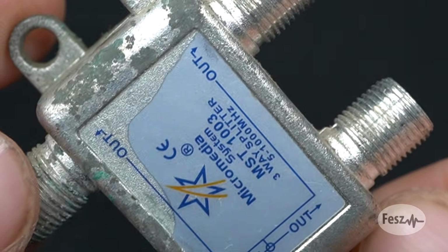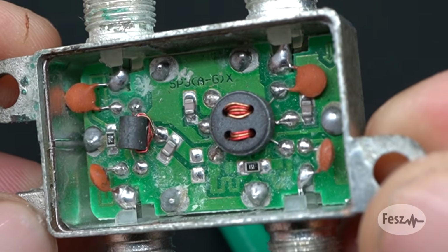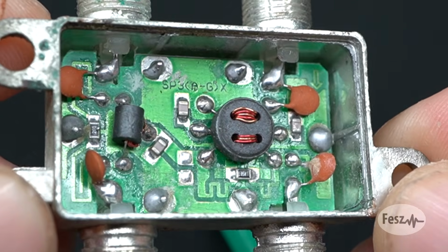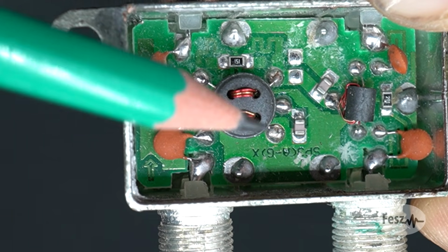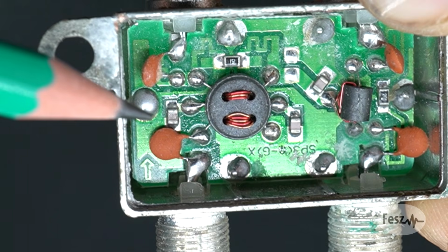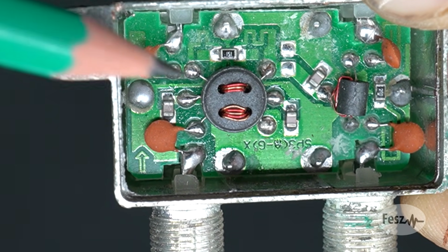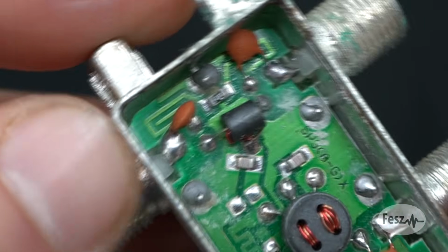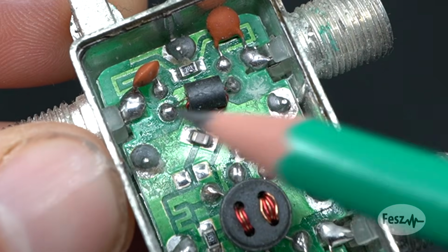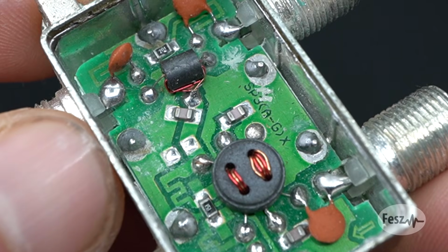What I have here is a three-way TV splitter, one that was built properly. This provides three isolated outputs using the principles that we've just discussed. Signal comes in through the bottom left port, goes into the first transformer, gets impedance matched, and then goes into the second transformer. Somehow both of these are built on the same core. But anyway, one side goes out, and the other goes into the third transformer, which again splits it into two, but this time into equal amounts.